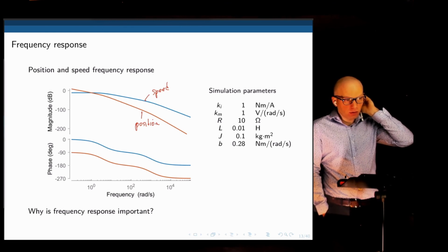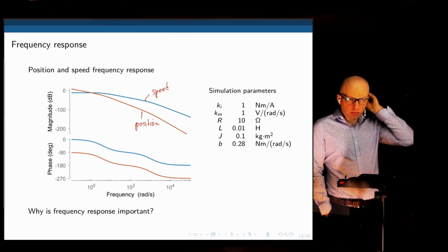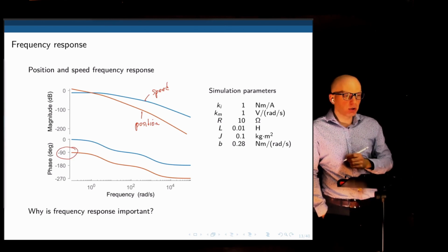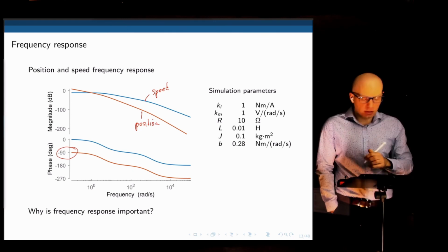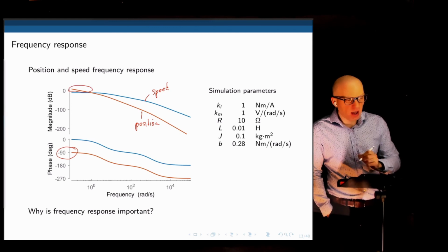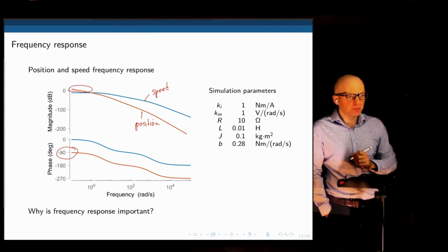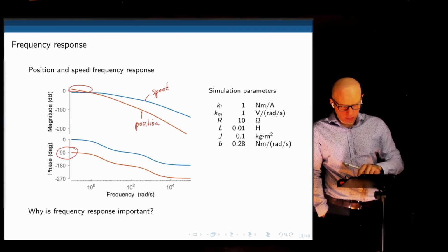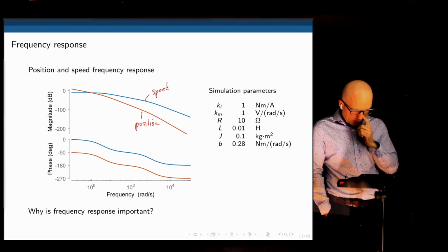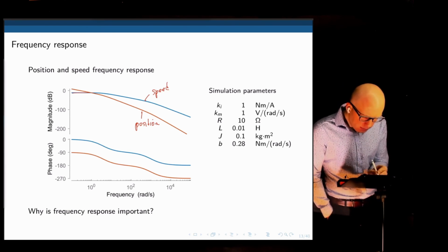The transfer function for position has an S on the bottom, so it's got a phase shift of 90 degrees down. Yeah, that's one indication. Very good. Because you have a pole at the origin, it starts at a negative 90 degrees, which is to say that originally here we have a slope of negative 20 dB, right, negative 20 dB, from the same effect. We can also tell this because this is flat.